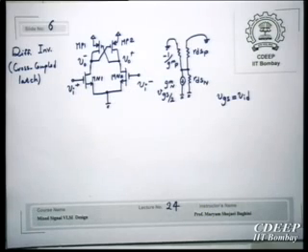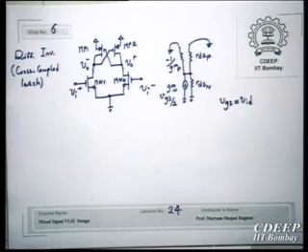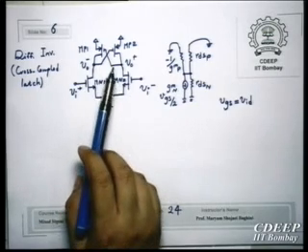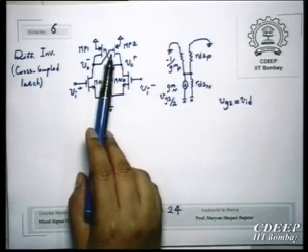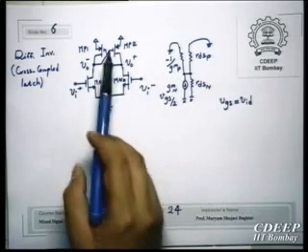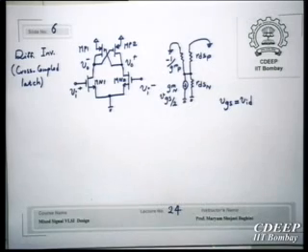It is the small signal model of this. Essentially, it shows a negative impedance due to this cross coupling. So effective impedance, if instead of connecting the gate of MP2 to VO minus, I had connected to VO plus, then I would have plus 1 upon GMP. Now by making this configuration, I am making a 180-degree phase shift because of positive feedback, therefore effective impedance now will be minus 1 upon GMP. So that's why it is unstable, and effectively this is what we want.